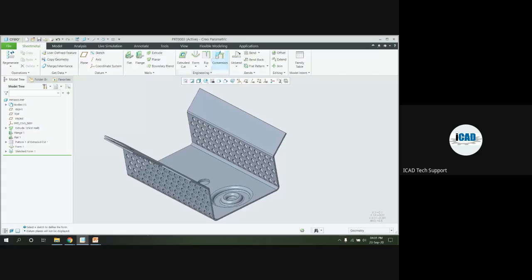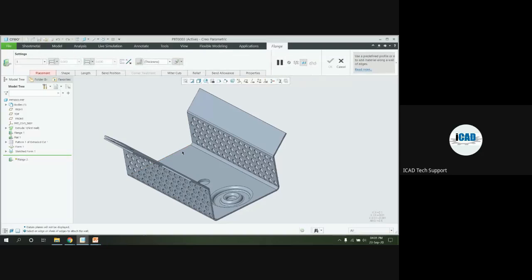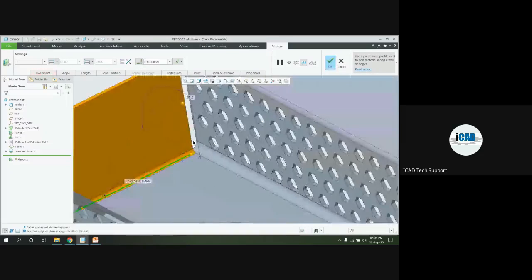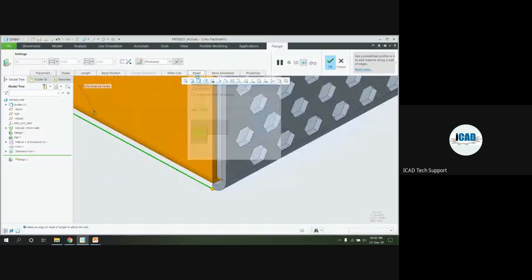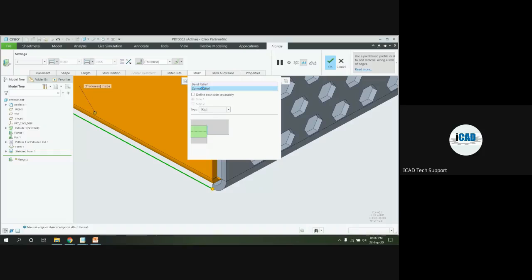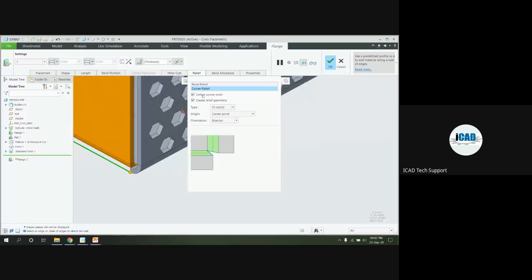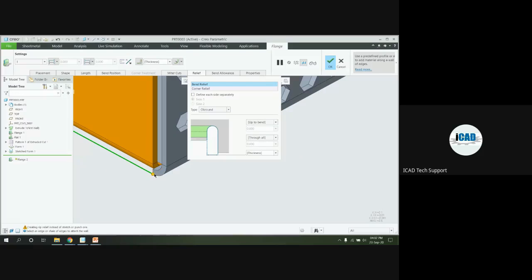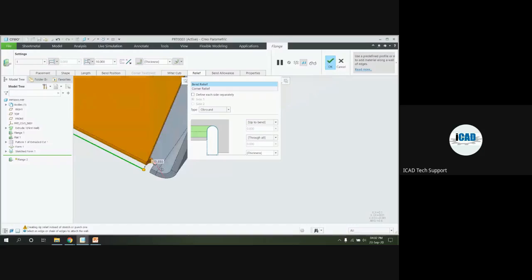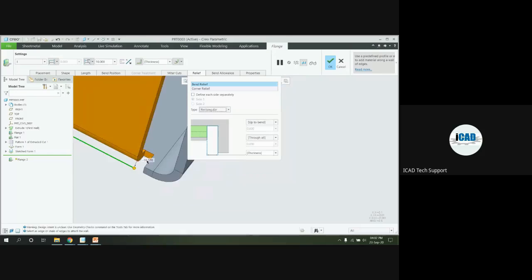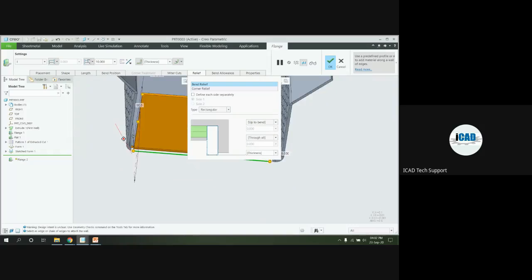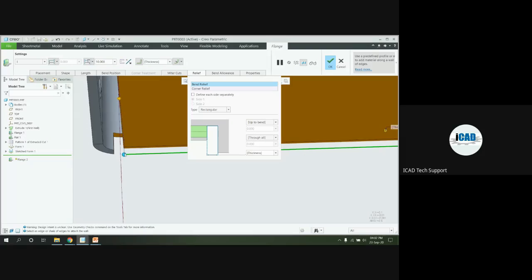I can create one flange at this specific internal edge. Here I can show the reliefs, the bend relief and corner relief, and how we can set them. Here I am giving the bend relief as oblong. Here you can observe this oblong, or if you want the relief as rectangular, now you can see from both sides the bend relief we can give at this specific area.